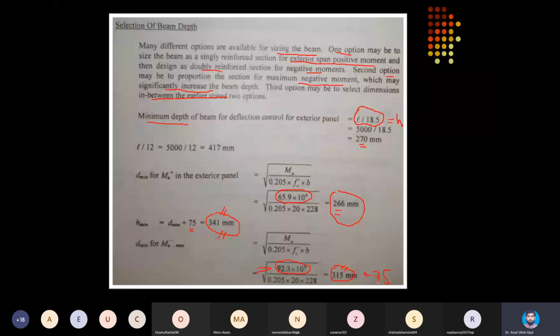And at interior spans where flange is in compression, neutral axis has traveled within the flange, so the T-shaped compression geometry is not in action as is present in picture D on slide number 5.